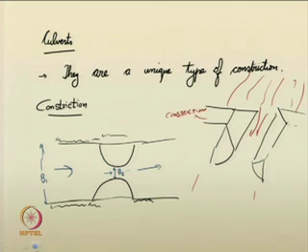We have already seen in the last class flow through a constricted way, means sudden constriction in the width of the channel. Those things we have studied. So, culverts are also a particular type of constriction, where the entire system is being closed, means the culvert is a closed constriction. We can say culvert is a closed constriction.